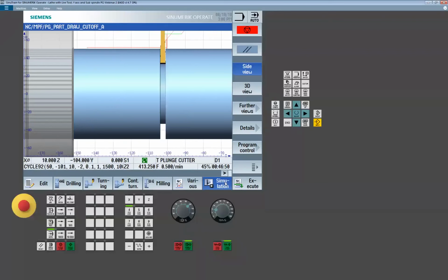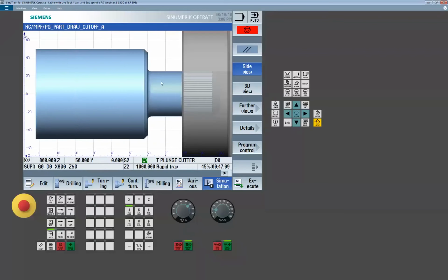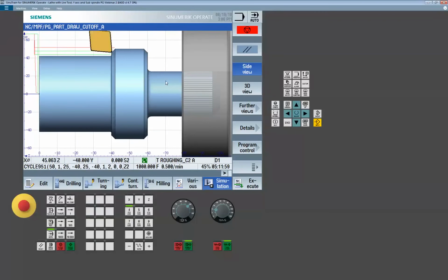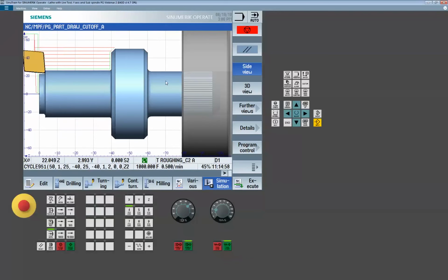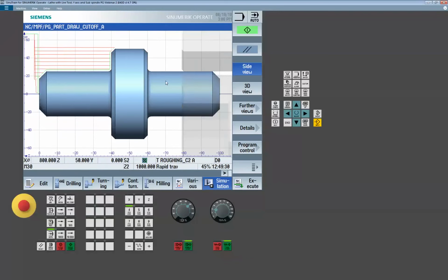here you go, here we're going to come in. You see the distance I have there is enough to machine the next part. So if the system came down, and that's that workpiece refocus. Just change the view for me so I don't have to worry about doing it. Nice little trick. And there we are. We've now done a full part transfer, withdraw, and cutoff. And really any one of the three scenarios we just showed you are probably going to be your most common scenarios of how you're going to handle picking and placing whatever toolpath and part geometry you're doing at this point.